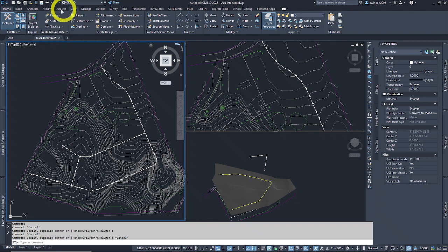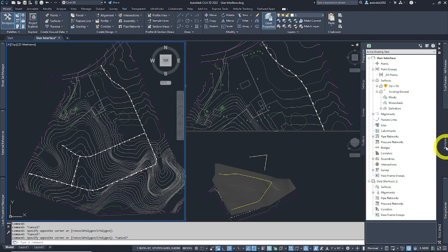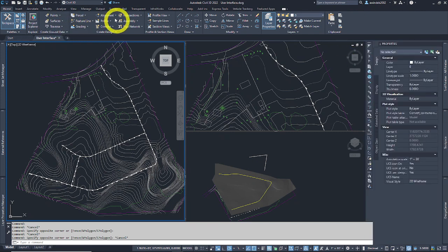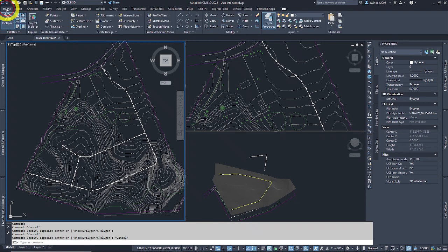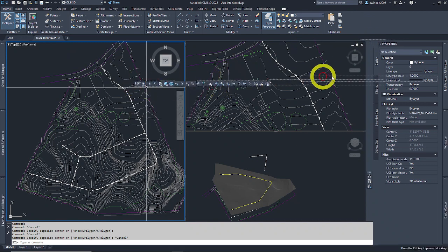So we're getting used to looking at this alongside our tool space over here, which is where I like to put it. You can put it wherever you want, with this file tree of your Civil 3D entities mixed with your options to edit entities, which there's more in here as we go along, especially in the Modify tab. But let's stick to the Home tab for now, which brings me to the last couple of areas of Chapter 1. It wants to talk about our transparent commands, which, it's funny, they still come in as a toolbar.